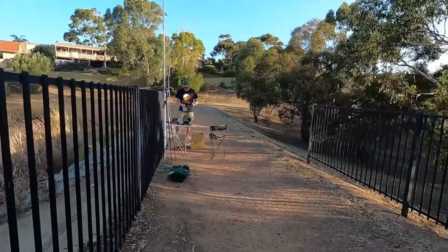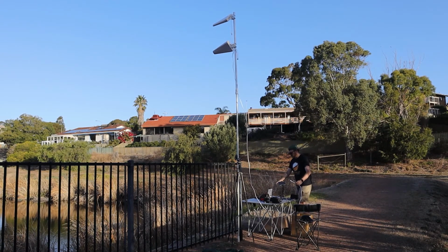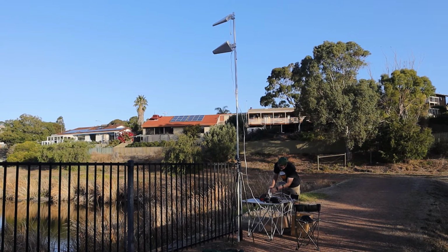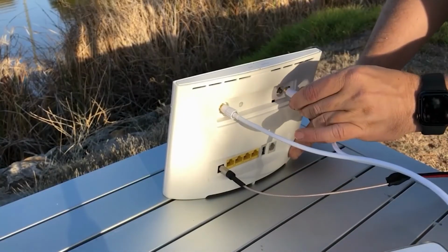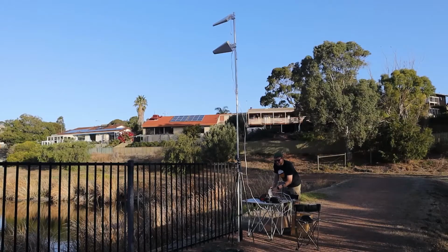Right, so what I will do is connect the antennas and we try again. Now this thing is on auto, so if I connect it, it automatically detects there's an external antenna connected. We connect both, because what I want to do here is first show the benefit you can get out of a MIMO antenna. So connect one, okay, connect the other one. I'm in a gully, so it's good, but it's not perfect. I won't get the best results I can get.